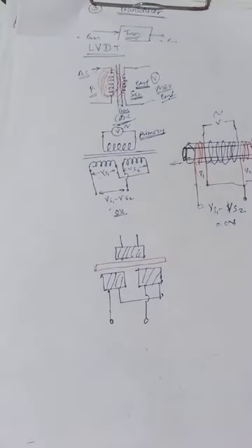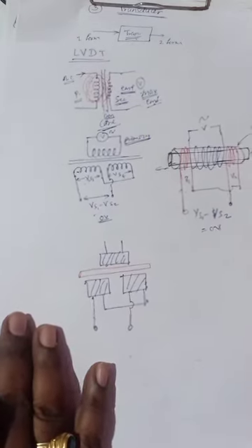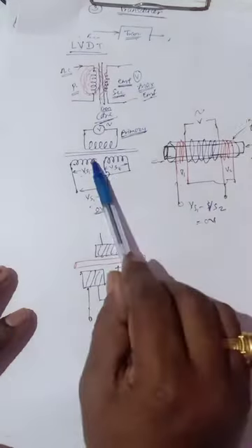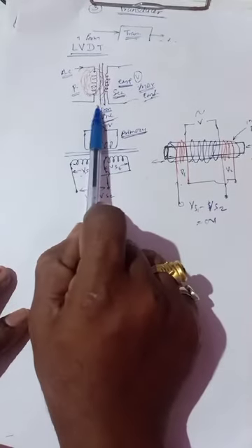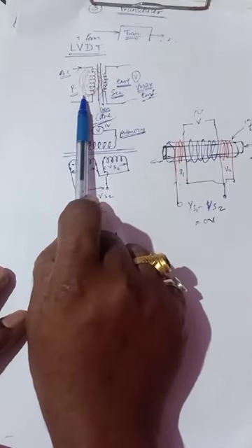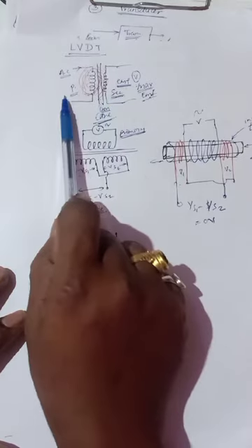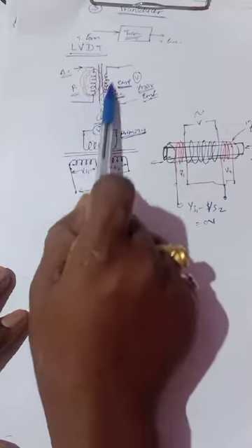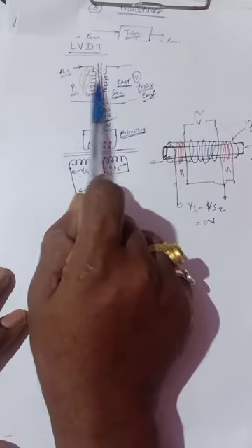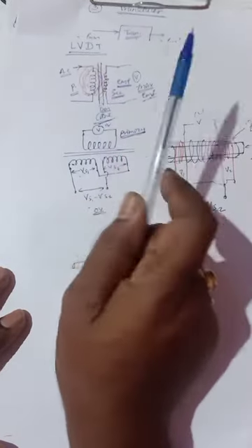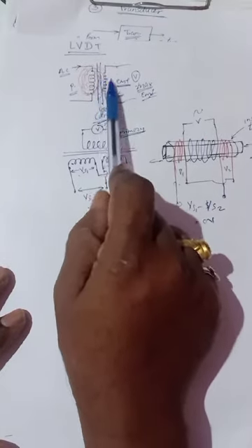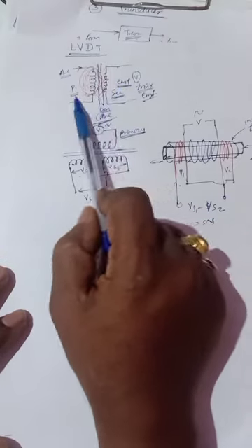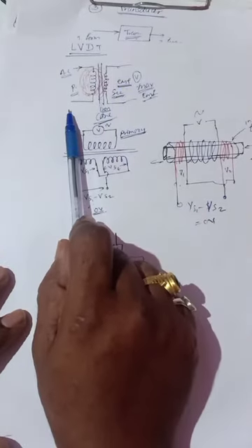Okay, so this is a transformer, but it is a differential transformer. What is meant by differential? Let us see here. This is the principle of transformer. It has a single primary and single secondary. If we apply AC current to this primary, then a varying magnetic field is generated at the primary and this is cut by the secondary. If this field is cut by the secondary, then EMF is induced in the secondary coil. So this is nothing but a transforming action.